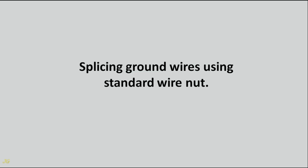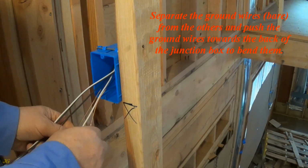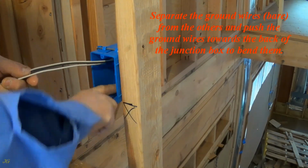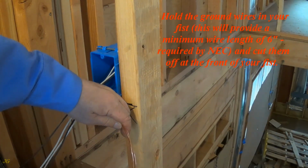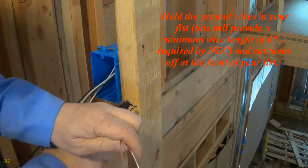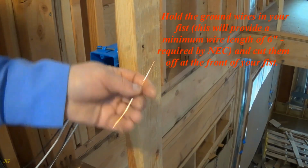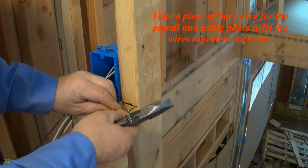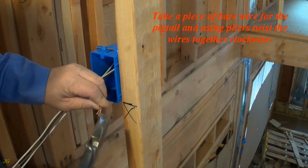Splicing ground wires using standard wire nut. Separate the ground wires, bare, from the others and push the ground wires towards the back of the junction box to bend them. Hold the ground wires in your fist. This will provide a minimum wire length of 6 inches required by NEC, and cut them off at the front of your fist. Take a piece of bare wire for the pigtail and, using pliers, twist the wires together clockwise.